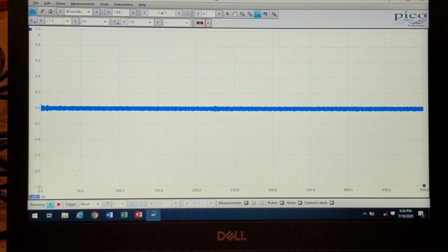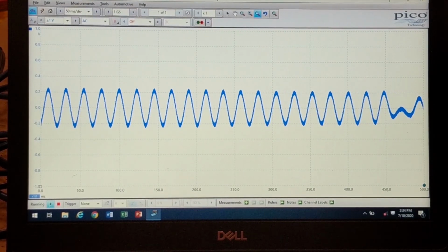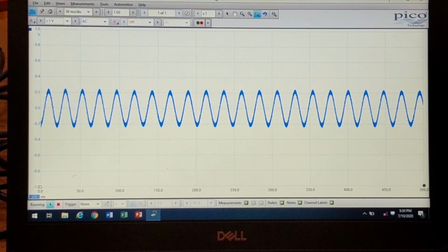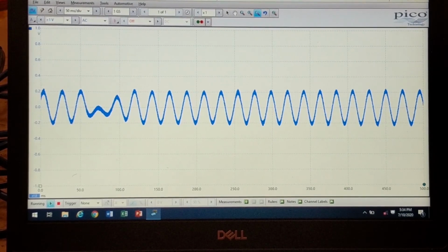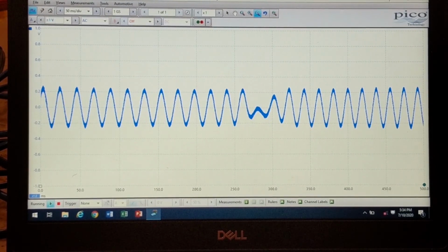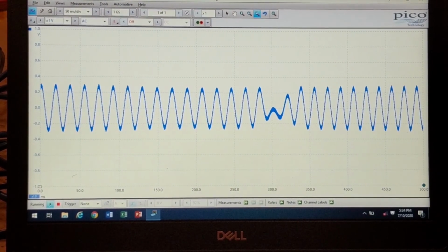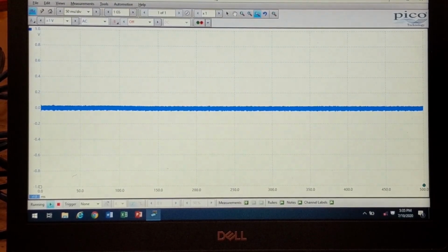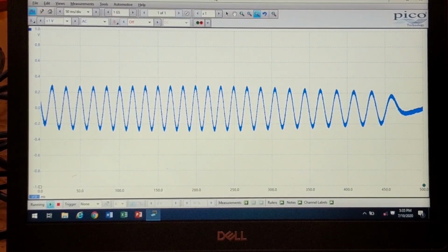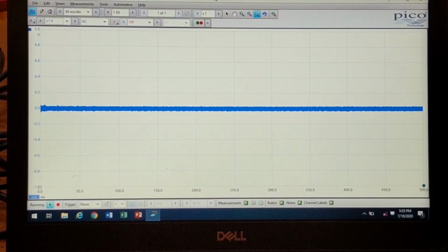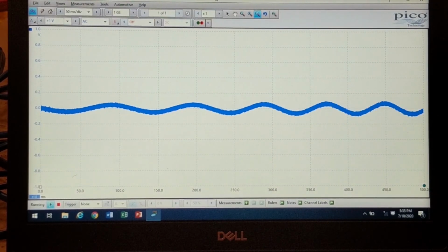So let's walk through a scenario. The ABS control module is monitoring the input from this wheel. Let's call it the left front wheel. If the driver needs to step on the brakes and this wheel stops, the signal goes from a sine wave to a flat line. Or if it's approaching a stop, it's going to be moving very slowly.